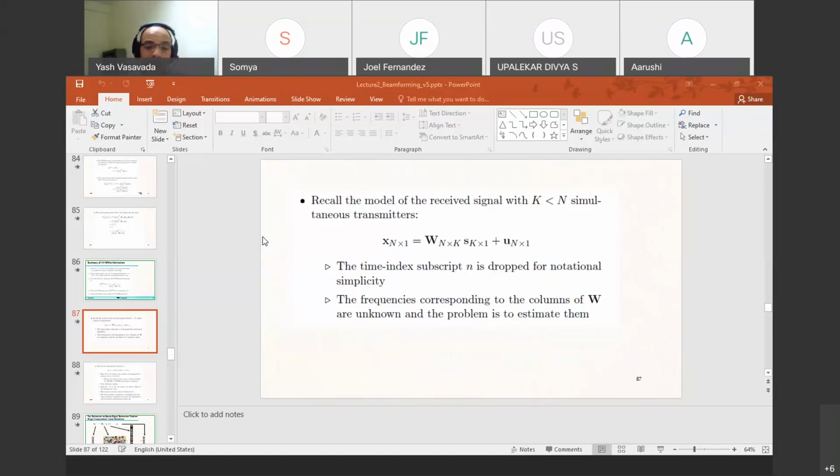Yes, the DFT filter will pass the actual frequency with a good strength, but unfortunately it will also register a pretty high strength at its output for a signal which is not even present. And that is coming because of that sinc shape profile that the DFT filters have, which we studied mathematically, and I think which is one of the problems that you have done as a part of your lab one.